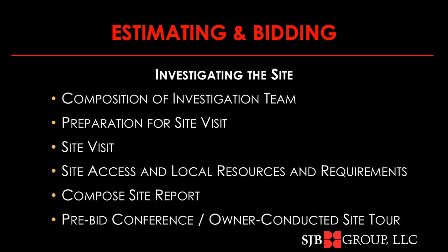You want to consider ground surfaces and the potential conditions at different times of the year, other than at the time of the site visit. You need to kind of evaluate what your clearing and grubbing considerations are going to be. You need to be identifying utility locations and size and the availability of water and electricity. And you may need to be evaluating some preliminary layout for any temporary works, plant, or camp that you may need in support of the project.